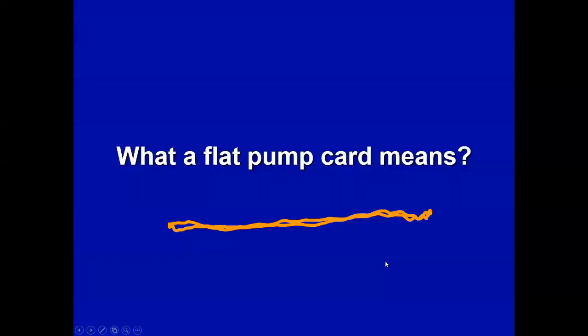And that takes me to one of the last topics, flat dyno cards. When you get a flat dyno card, you may think of multiple reasons. If you make a measurement and you see a flat dyno card, that could be a parted rod, either shallow or deep. But if you have a problem in the pump, with the traveling or the standing valve stuck open, you're not pumping. You can see the plunger going up and down, but there are no fluid loads being picked up or dropped. So there's no load fluctuation, and the result is a flat dyno card.